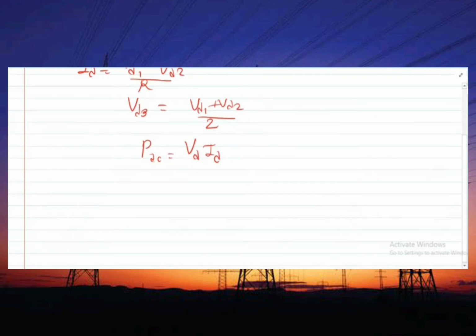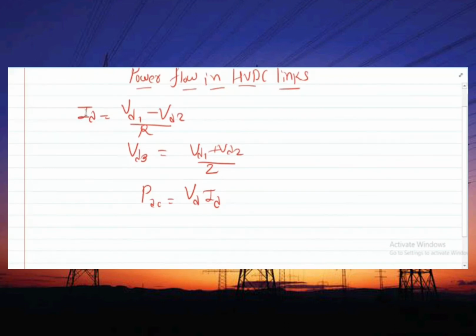On the DC side, the voltages VD1 and VD2 at both ends of the DC line have definite relations to the corresponding AC voltages, which depend upon the position of the tap changing transformer or the delay angle of the converter. So we usually hold VD2 at a certain value by voltage control of the inverter terminal, and the current ID is controlled by the rectifier terminal.